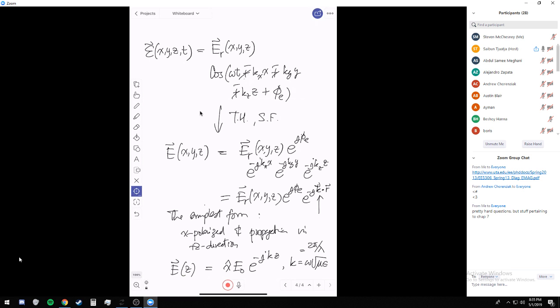and then do some analysis. And of course, to determine the power density, the time average power density is 1/2 real part of E cross H conjugate, right? So that's pretty much fixed. We didn't have a chance to derive that equation, but that's a pretty standard equation. I'm not too worried about the derivation, but you should be able to understand what those formulations mean.